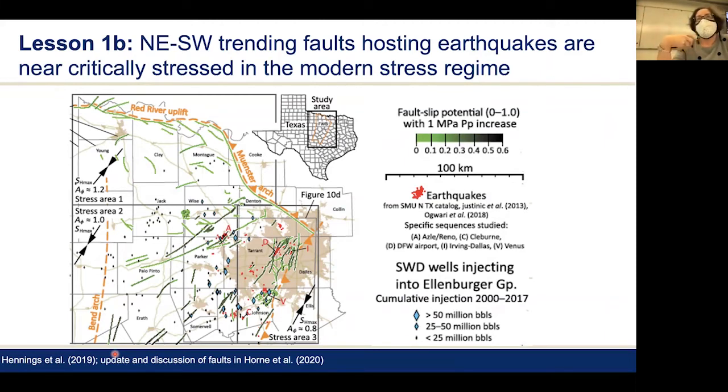And those production wells actually generate a lot more wastewater than the wells to the west or to the east where the Viola-Simpson exists. Basically, it looks like if the Viola-Simpson's not present, frac energy can break into the Ellenberger, which had its own natural brine in it. And when they produce the natural gas, they're pulling water out of the Ellenberger.